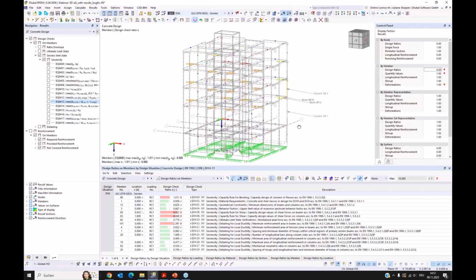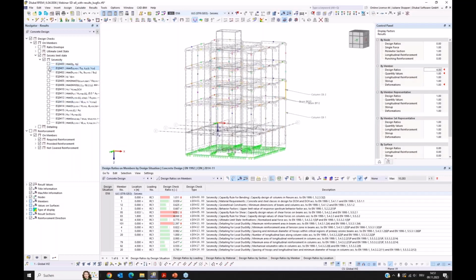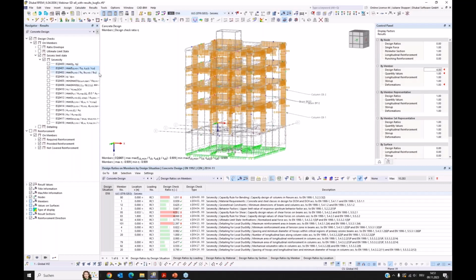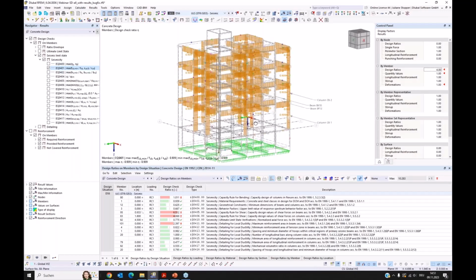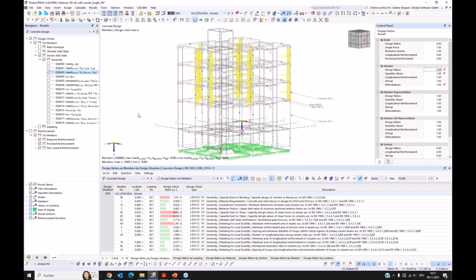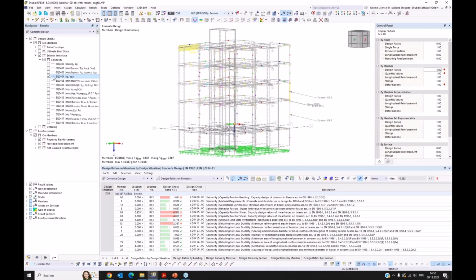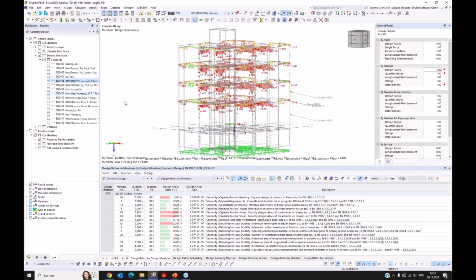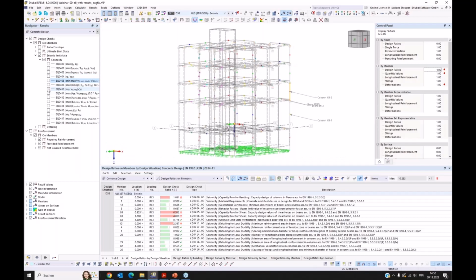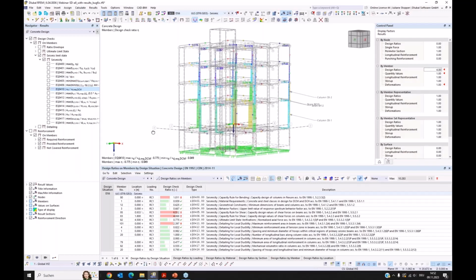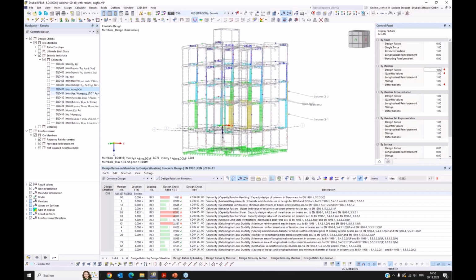So here we have the strong column weak beam rule checked for the nodes. Then we have here the material checked for all members, and we have the geometric rules checked. And yeah, I checked the behavior factor just for one, but it's valid for the whole building. I only did the calculation just once. These are the shear results we looked at, and here we have a check according to the normal force in the columns and compared with the limit value.